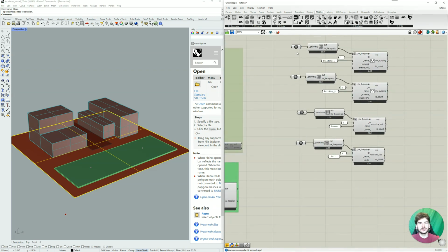And now we move on to our grass area. This is a 2D plant. So in ENVI-met we have 2D and 3D plants, and stuff like hedges or plants, agricultural plants are all considered 2D plants, and 3D plants are basically only trees. So we're gonna select the 2D,